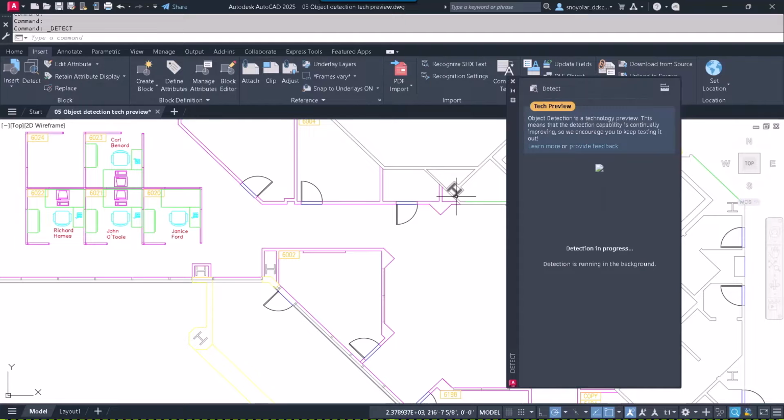A palette appears in Review mode, initiating the process of determining and detecting groups of entities. It identifies objects that can be converted to a block or an existing block, searching for any incorrect instances to report to Autodesk. This technology is constantly evolving, and the palette plays a crucial role in this ongoing development. The crucial factors for these elements are that it is specifically designed for architectural elements, currently detecting doors, toilets, bathtubs, urinals, symbols, and generic lighting fixtures in the environment. It detected 13 sets in 87 instances.